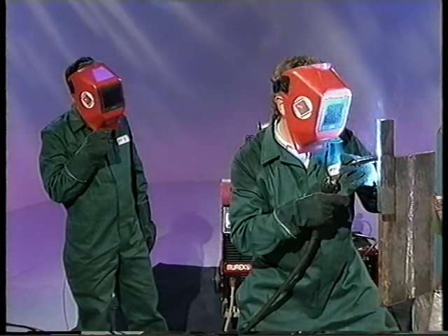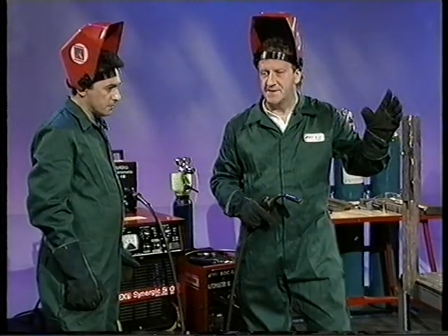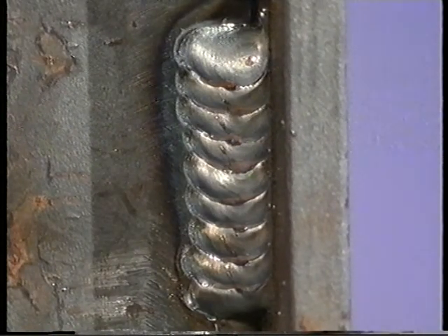So as you can see there, the wire is going right into the root, making sure we've got good penetration, dwelling at the sides to allow the weld to spread out and sit flat, keeping this triangle going to get good fusion all the way through. I noticed that each time you're going up the work rather than down. Yes. On any sort of thickness above, say, 3mm thick, you should always go vertically up to ensure good fusion and penetration. On 3mm and below, yes, you can move vertically down.